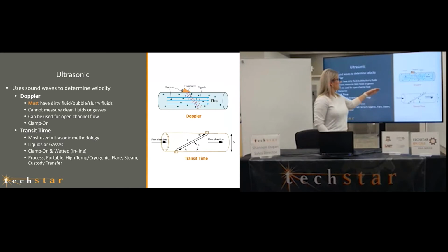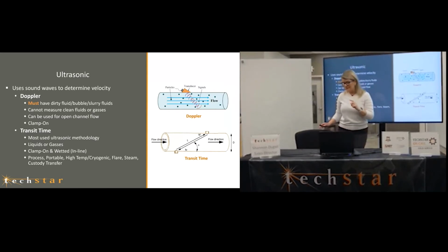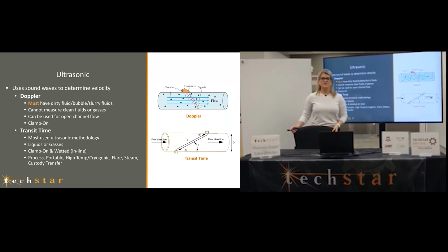This is represented here. In order to have a Doppler meter, you have to have something in the line to bounce the signal off of. So you can't use it for really clean fluids because there's nothing to bounce the signal off of. If you think about it, it's kind of like your fish finder. Your Doppler signal is going down, finding fish, and then coming back up so you know where that is. So it's very similar to this.